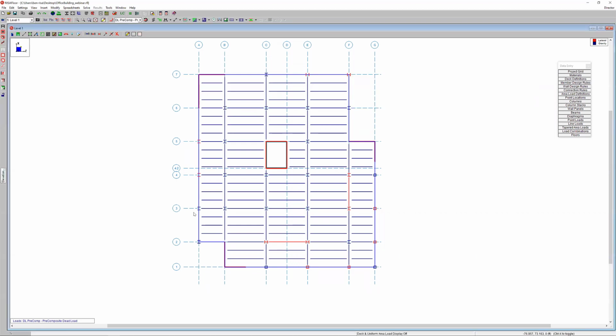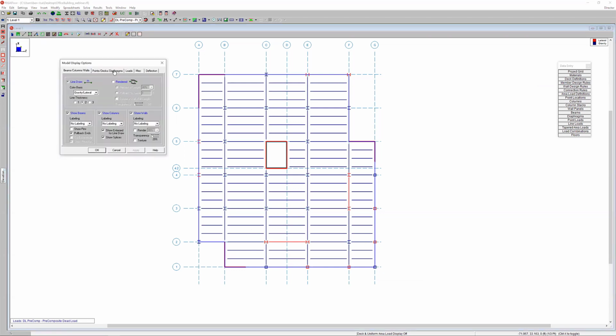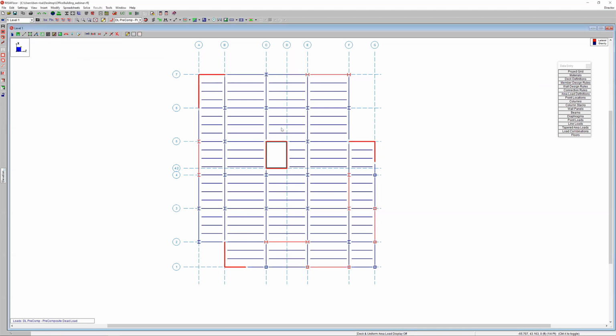And so we're going to use those pretty standard design rules there, and I'm going to go ahead and also, just from a visibility standpoint, I'm going to turn off my diaphragm. Even though I have a diaphragm, I'm just going to turn off its visibility for just a moment. And so let's pop over here and say show diaphragm edge. Okay, so now we can plainly see our different lateral systems. So we've got our walls are part of our lateral system. We've got our frames that are part of our lateral system.